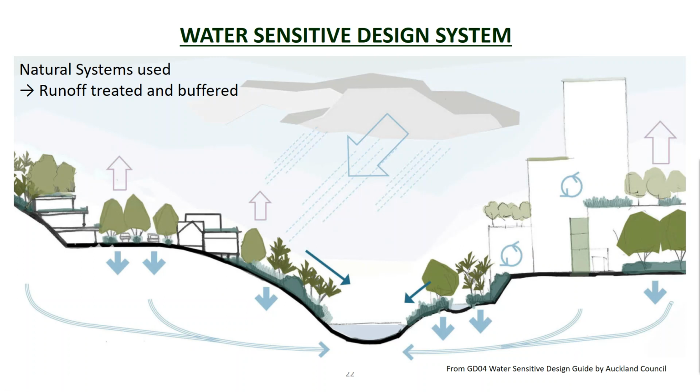So we're going to talk about rain gardens and things like that. They hold some of the water in. So the flow that is going to the water bodies is slowed down considerably. Instead of having a whole lot of water all coming in at one go, you've got the same amount of water coming in over a period of a few days or something like that. So the stream doesn't get that big peak flow that we saw before.